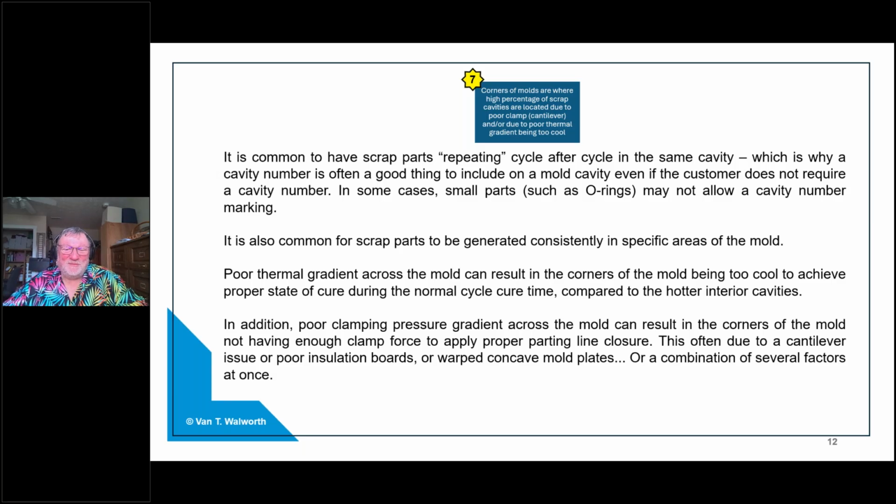What could possibly happen? Other companies have kind of got the idea that we don't need to exceed the area of the ram too much with our cavities and kind of stay away from the corners. That would generally be a good idea. And so many injection molds tend to stay within more of a round circular pattern.